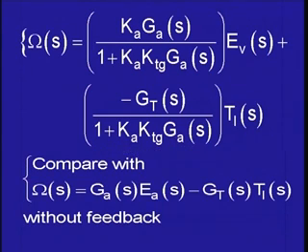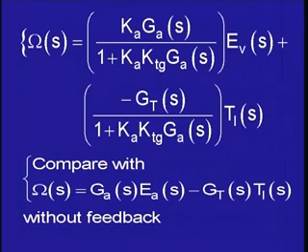So, that means the value of the applied voltage which was used earlier will not now be the value of the reference voltage, and this is something we have seen already. I was talking about a numerical example with armature voltage of the order of 230 volts, whereas the reference voltage may be of the order of 20 volts. But that is alright, because this EA is multiplied by GA, whereas ER is multiplied by GA into Ka divided by this denominator factor 1 plus Ka K tachogenerator Ga.